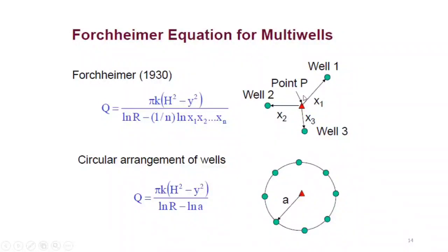Okay, so in this situation, of course you already know their positions, where you have installed these piezometers or observation wells. So you know their distances x1, x2, x3. You have the pumping well. So using this relationship, you can again calculate the flow. Okay. Actually, it's a two-way relationship. If you already know the flow because you are pumping out the water, so flow is normally with you. So Q is with you, and you can indirectly get the value of K. Okay. Or you have the K, you can get the approximate flow to the well, because it's a two-way process.